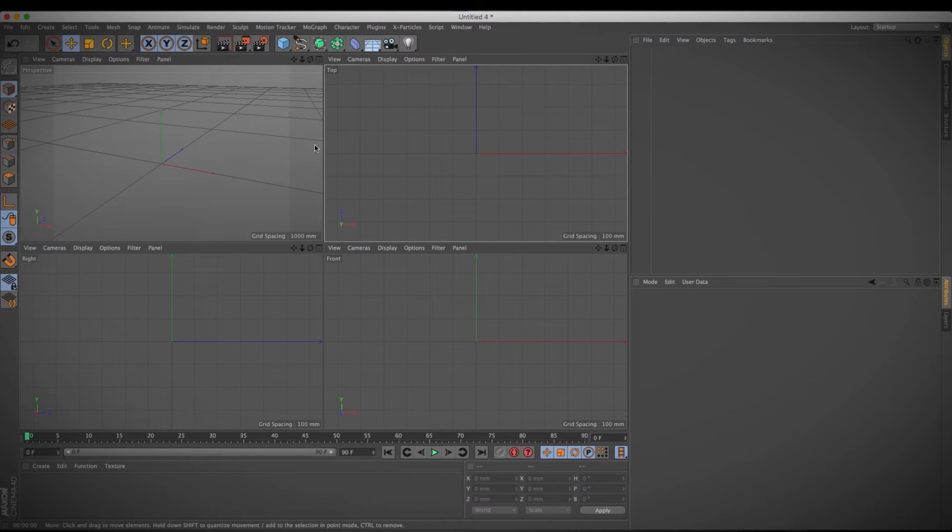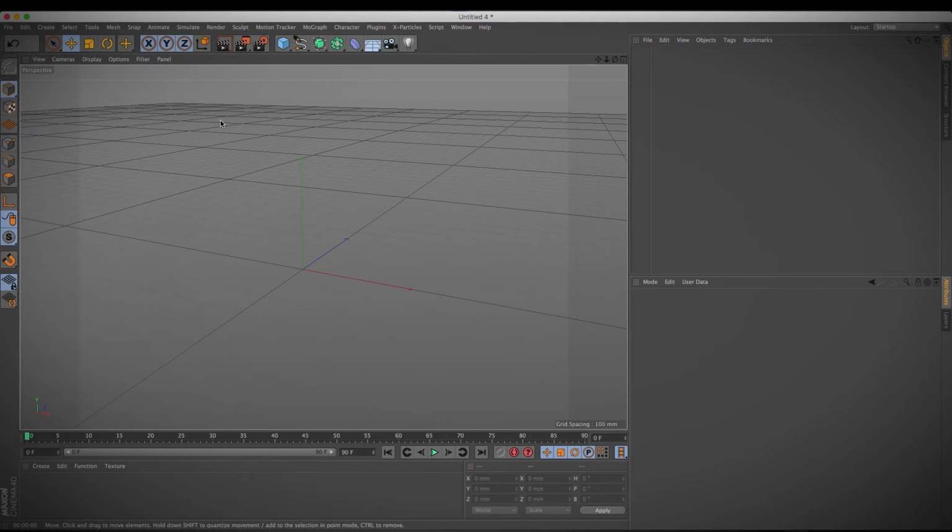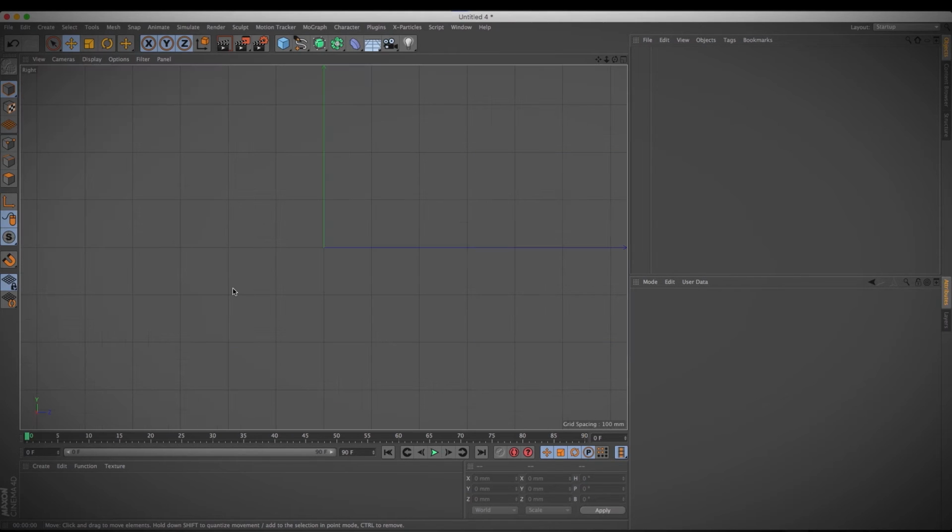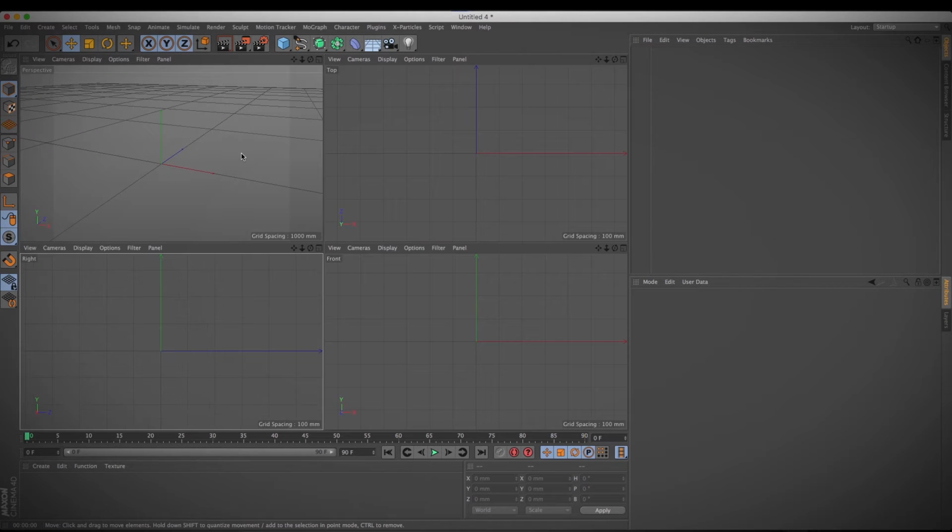You can also access this function using your mouse. Should you have a 3 button or 2 button with a scroll wheel, by clicking the scroll wheel on the background of each window, it does the same operation. Clicking again returns to the previous view, clicking each window expands the view, and clicking again returns the view to home. These little icons appear in all the orthographic views to make navigation easy.